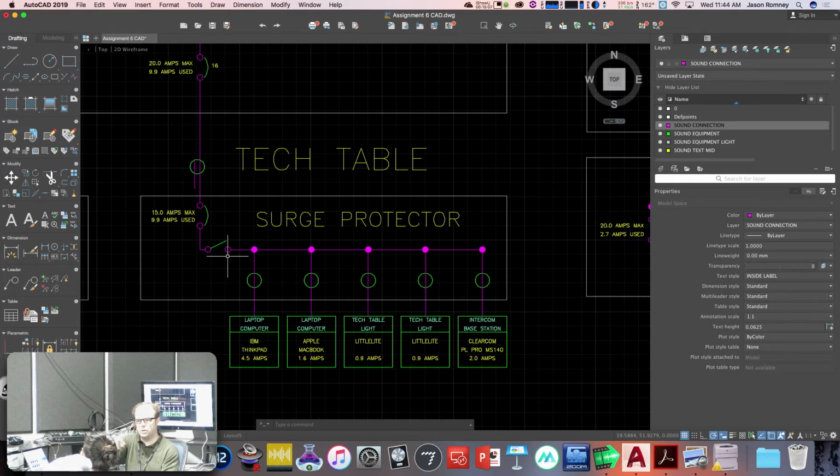On most surge protectors, those are separate things. Some are the same, some they're separate. But electrically speaking, it makes sense to just draw them separately. So I've got a 15 amp breaker in that surge protector and a power switch before I get to any of the actual receptacles.